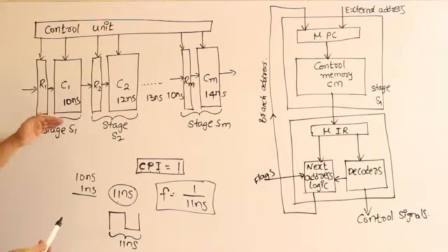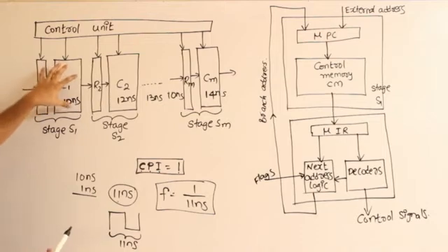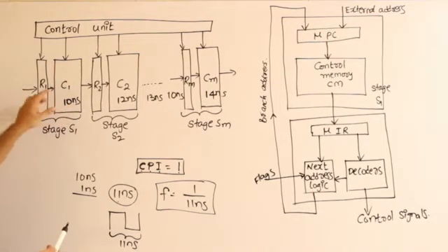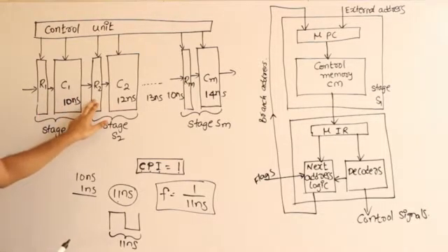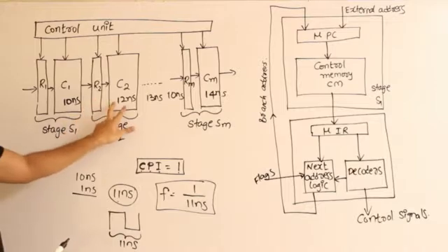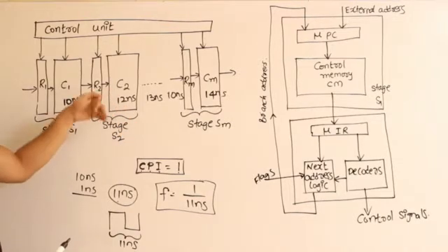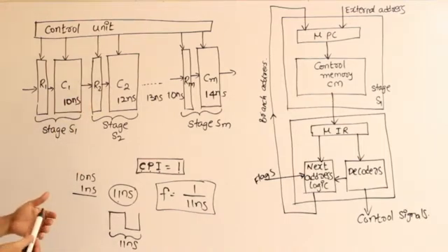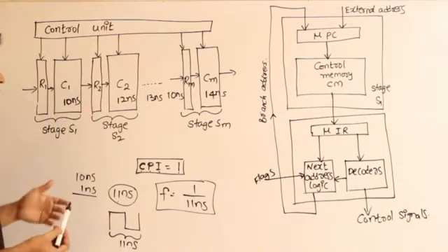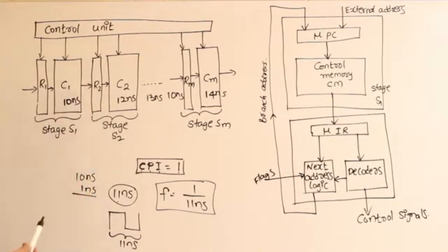If you fix the clock to the smallest required time, let us say 10 nanoseconds is the least time required by any unit, so 10 plus 1, which is 11 nanoseconds, then in one clock this information will be pushed onto the next stage. But this particular unit is still processing, it didn't push out its data, so there will be overlapping, and the pipelining will not function properly.